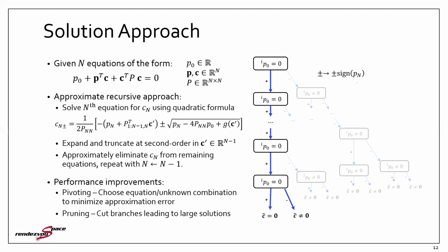So the constraint equations governing the IROD problem are homogeneous, and so all of the scalar terms, at least in the initial system, are actually 0. This tells us that one branch of the tree will directly lead to the trivial solution, which would place the target spacecraft in the same state as the observer. The magnitude of the estimated relative state constants tends to increase as we move away from this trivial branch until our small value assumption breaks down. Thus, only a small number of the adjacent branches really need to be considered.